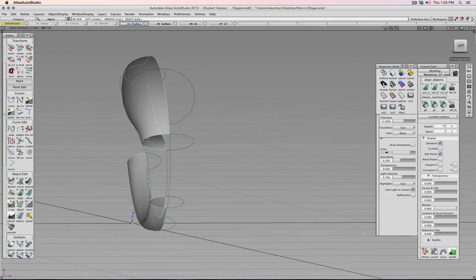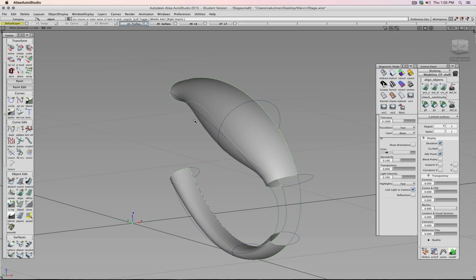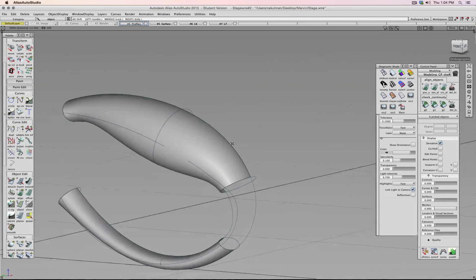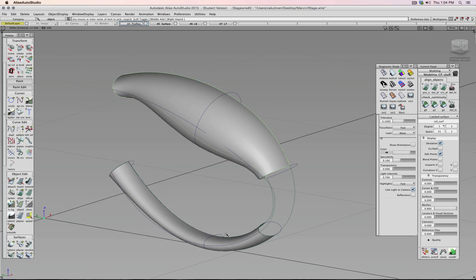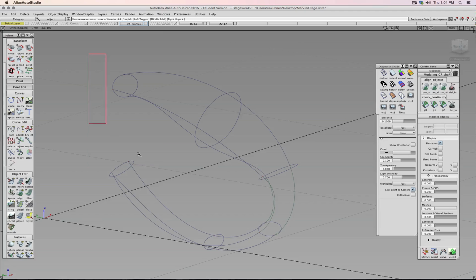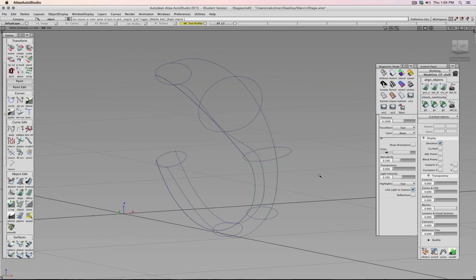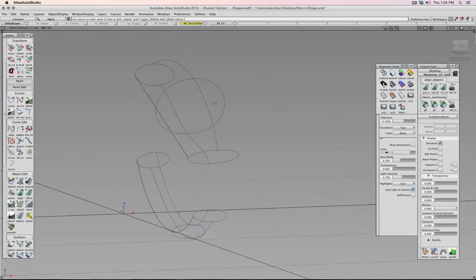So probably what I will have to do now is create some nice midlines carefully, and then I have to start cutting also my arcs into quarters. So I have a quarter rail, a quarter rail, quarter rail, quarter rail, and then I can blend between those. Okay, so let's try out that strategy. So those surfaces, maybe for the moment I keep, and everything here I copy and paste, put onto new layers so I do not maybe by accident mess up my original lines. Those I don't need at the moment.